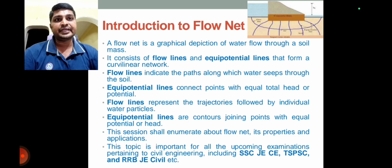Flow lines indicate the path along which water seeps through the soil. The equipotential lines connect points with equal total head or potential head. Flow lines represent the trajectories followed by the individual water particles. Equipotential lines are contours joining points with equal potential or head. When we observe the diagram, the flow lines and equipotential lines are presented.